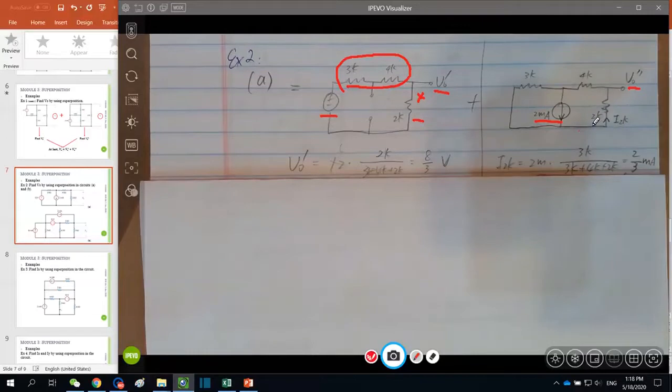And you're seeing 2 kilo ohm here and 4 kilo ohm here. These two are series connected. So this is one branch, which is parallel with the 3 kilo ohm here as the second branch. So these two are sharing the total 2 milliampere current. So obviously we are looking for this branch current by current divider. And be careful, due to the current direction of the source here being downwards, the current through the 2 kilo ohm is upward. Okay, this is a very, very important thing.